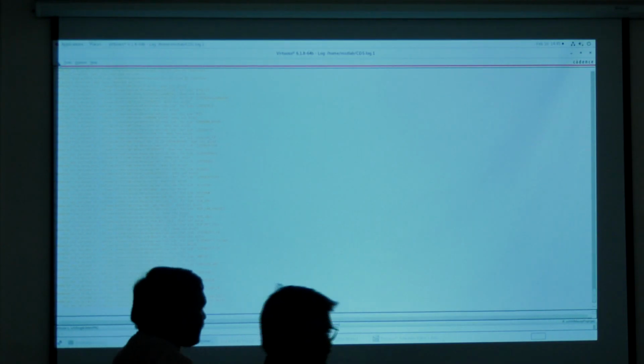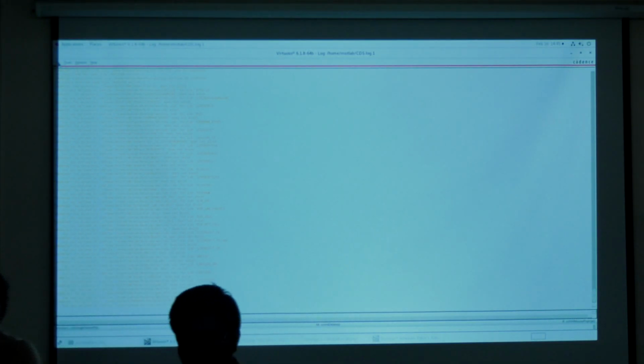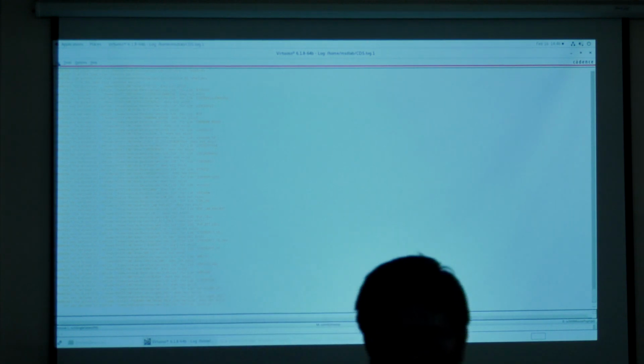Now everyone look at the screen once, who have not created the circuit. This is the window you are going to see after opening the tool. This is the CIW window. Here you need to go to Tools. I think everyone created the library.